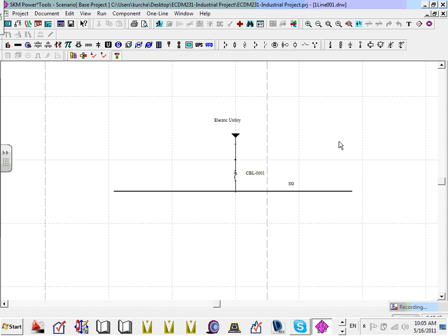Some other engineers, guys, do it differently. You can use a schedule and put the actual lighting circuits in the load. They do it because they want to print the panel schedule from this software. That's how they do their panel schedule, at least last year and the year before. We're not going to do it this way because it's time consuming. If you want to do it with the schedule, you have to go to every lighting circuit and put it in the software. It takes forever. At this time, we're not going to do it. We're going to do it the summary way.